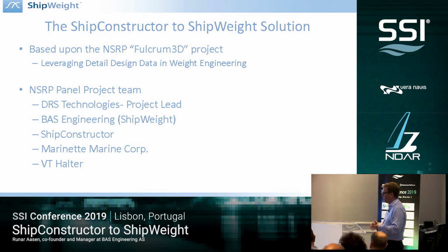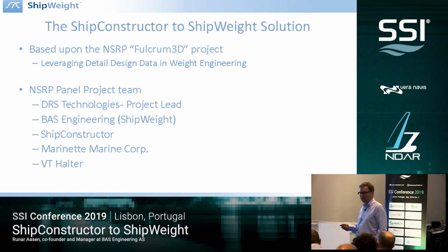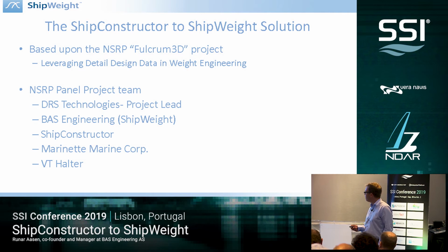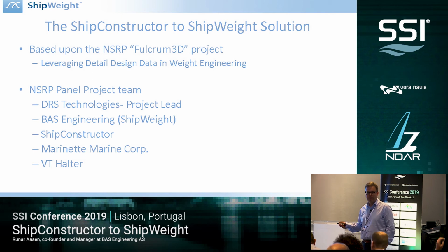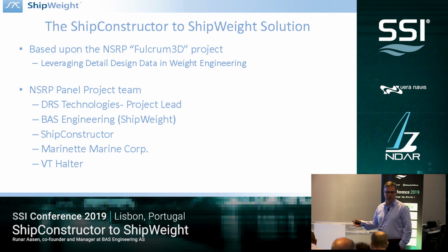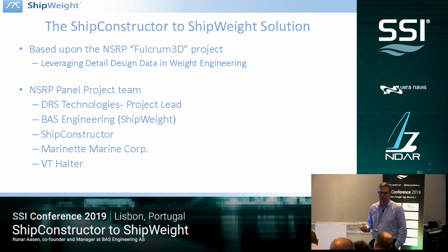And out of this project came a middleware which was called Fulcrum 3D, which some of you might have heard of. And this was the basis for the solution that we have implemented directly in Shipweight. We were able to connect to the Fulcrum 3D and import the ShipConstructor data through Fulcrum 3D. But now in the newest version of Shipweight, we can skip that and import it directly. And this is how. It all starts with a smart export from ShipConstructor.